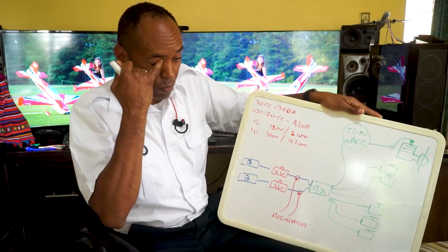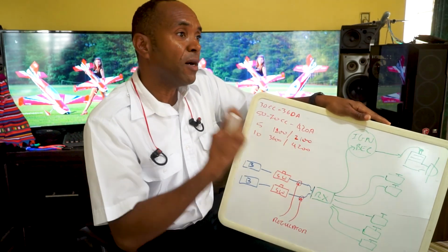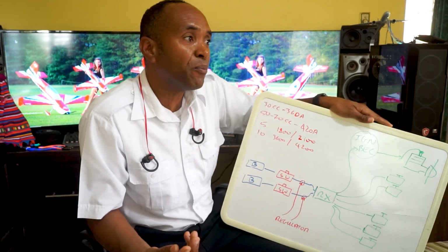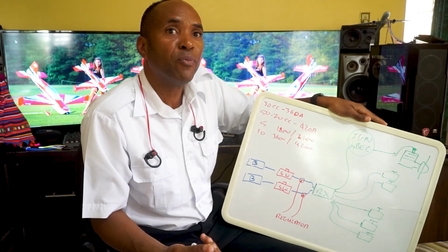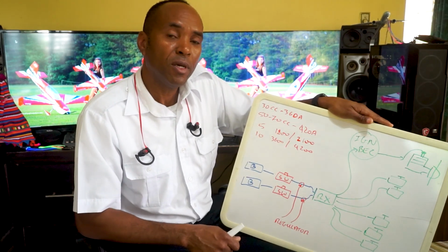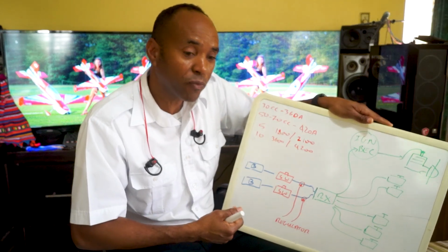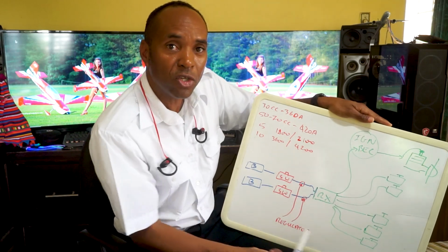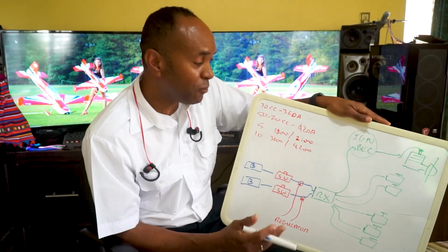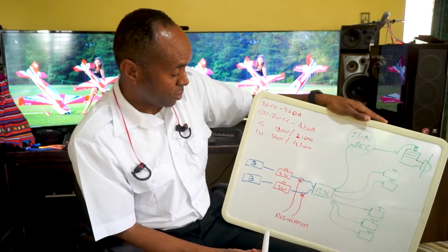What I mean is this now. Let us say you have high voltage servos, right? Each battery, like say a LiPo battery, will have a reference voltage of 7.2 volts. When the battery is charged to the peak, it is going to come up to 8.4 volts. So each component in this system must be able to manage 8.4 volts continuous. If not, you're going to have a problem and something is going to burn out, right?